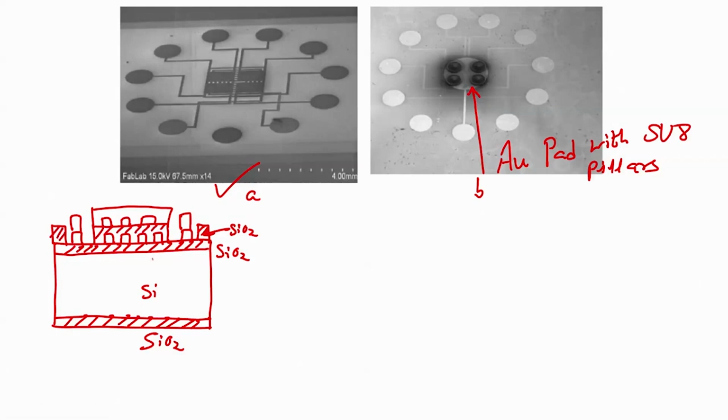here insulator. Then what is this one? This is your micro heater. Then what is this one? This is your interdigitated electrodes. What is this one? This is your piezoresistive material, correct. This is your A, and next is we have to deposit gold, but like I said, we cannot deposit metal on piezoresistor. So, what is the next step?